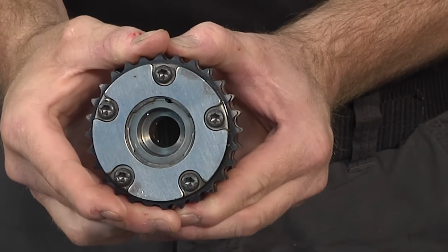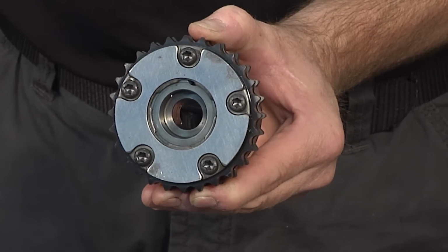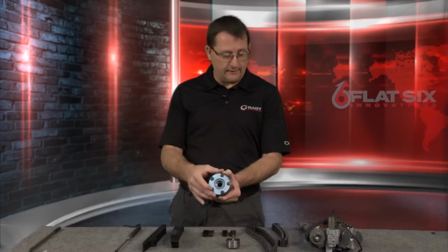So I'm just trying to help set the stage here for how many components the 3-chain is missing over the 5-chain. The 3-chain system is newer and is a lot better in its ability to adjust not just RPM, but also from a load perspective, okay? And this unit, as well as the chain adjuster here, are hydraulic adjusters. So the engine oil plays into this, okay?